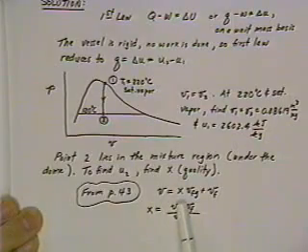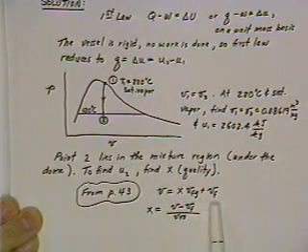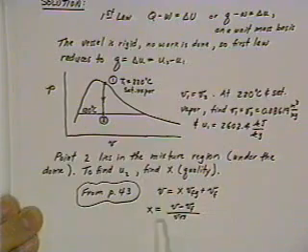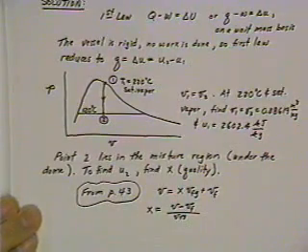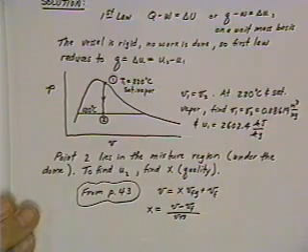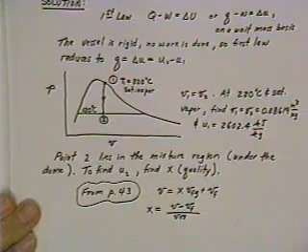So V is equal to X VFG plus VF. The quality is the key term you always have to find whenever you're in the mixture region, in order to find the properties at that particular point.